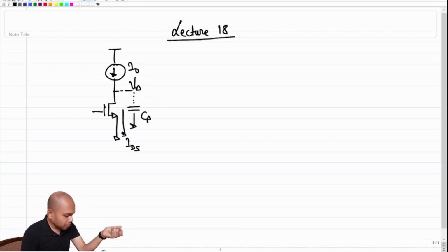And what was the fix? The fix was to decrease the overdrive voltage, because the information that we are attaining from the fact that VD is going down is that the transistor has higher overdrive voltage than required, which means we need to reduce the overdrive voltage. So how do I correlate the voltage of the drain and the requirement of the transistor?